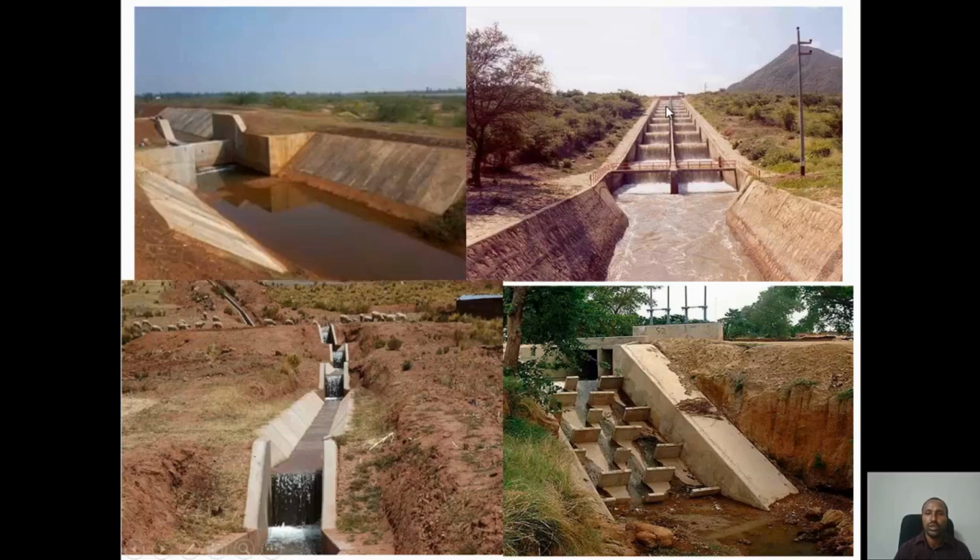This is drop, drop, drop, drop, drop, drop. Then it will dissipate, then slowly it will go to the downstream part. And this is also similar, you can see. Once you provide a chute, you may have energy. Then it will go, then drop the first one, then when it goes to the second, to the next, etc., the energy is dissipating. It will not affect the downstream part.